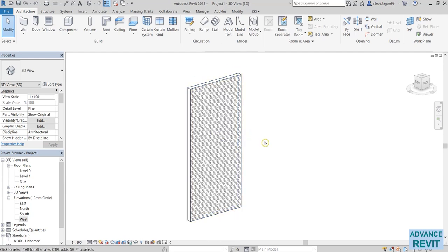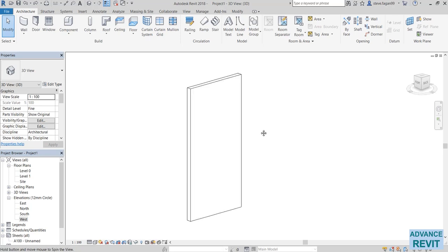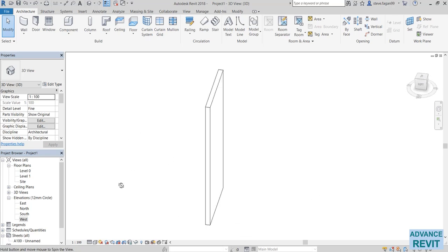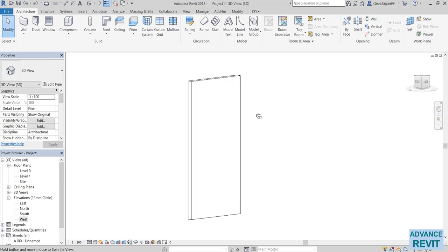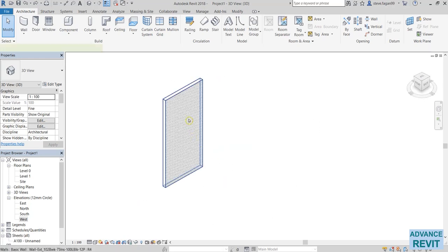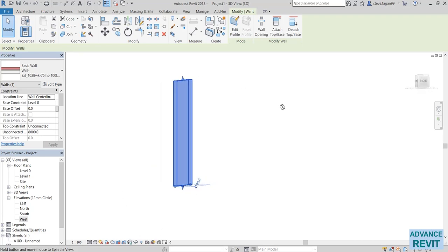In order to orbit the view, we need to hold in Shift, hold in the scroll wheel, and then we can move the cursor to orbit around an object. To make the object centralized when we orbit, we select it and then orbit.